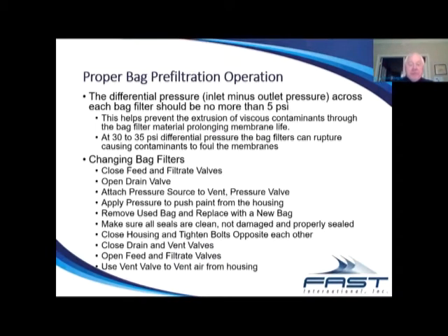How to change a bag filter? It seems pretty evident. Doesn't seem that difficult, but we've seen a lot of things done that were inappropriate. Of course, what you want to do is close the feed and filtrate valves off the manifolds, open the drain valve, and then pressurize the vent pressure valve to be able to push the paint out of the housings.